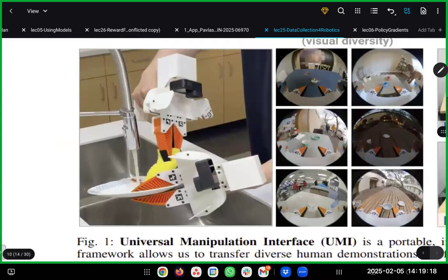So for this particular paper, you can get a 3D printed copy of the manipulator that will be mounted on the robot. And then you can also hold that in the hand, and it'll record basically the open and closing action for the hand. I believe there's also an IMU and a camera on this. So it's basically all the end effector pose and gripping information that is used to actually determine where the robot arm will go. And this is possibly a bit nicer because here there's no, at least versions of, dynamics mismatch, especially contacts, because contacts are some of the worst places to have dynamics mismatch.